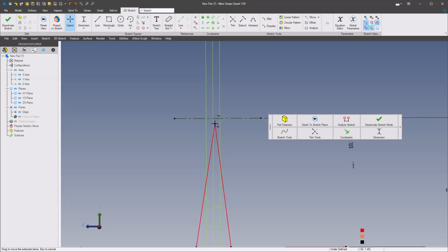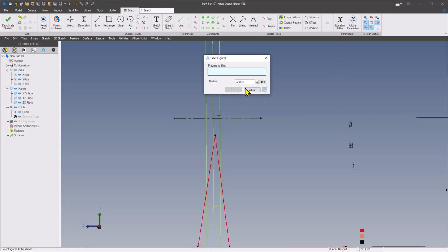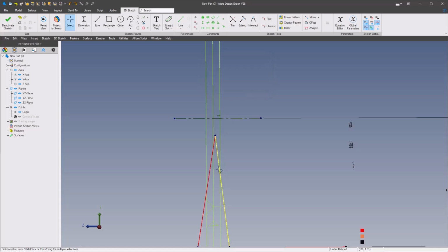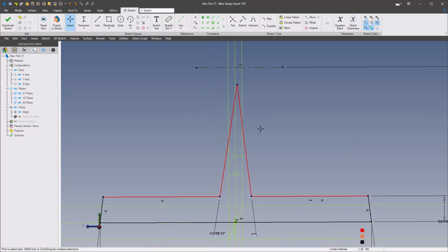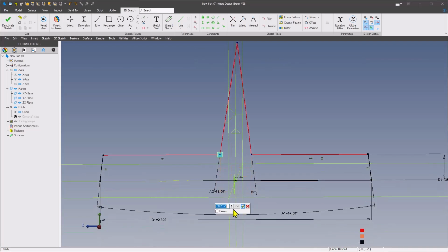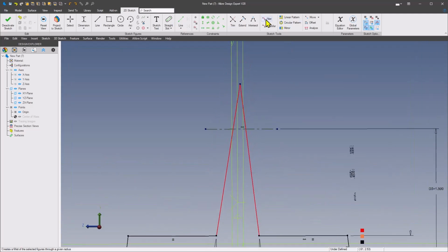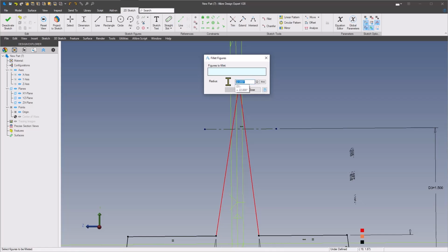Now, let me see, that's not a full round radius on there. We have a dimension here, base across here is going to be a 1/2 inch. So let's do a fillet. Start out here 0.25.